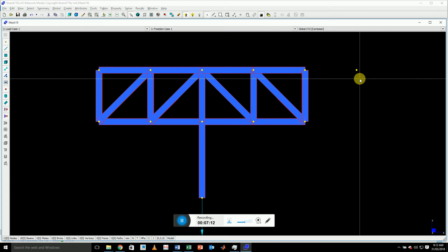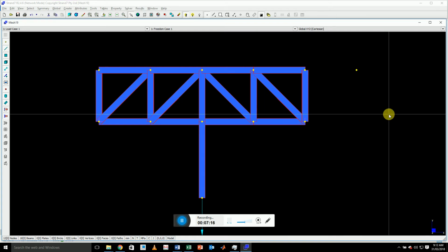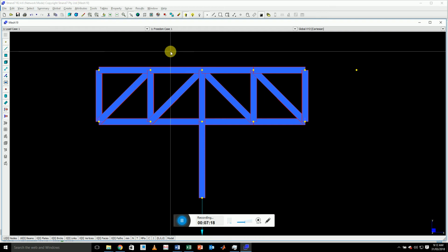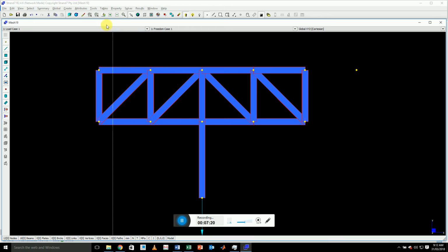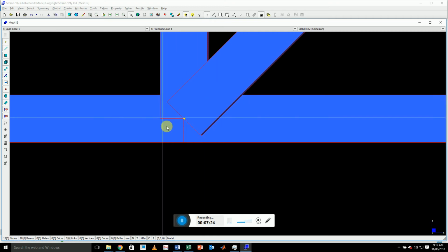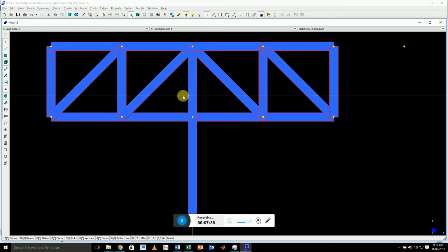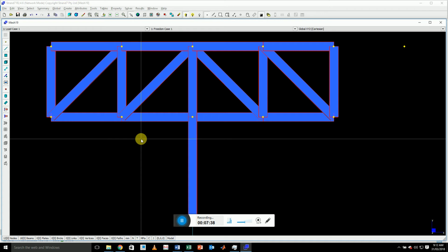It's a node, it has no properties, but if I had a bit of beam out here connected to nothing, that would cause us problems. Just to point out very quickly, yeah, the joints in this model are basically just assumed to be perfect. Strand just goes, yeah, I'm assuming you got your joints right. That's not what we're modeling here. If you want to model joints, you need a more complicated model, which Strand can do, but we're not going to get into.